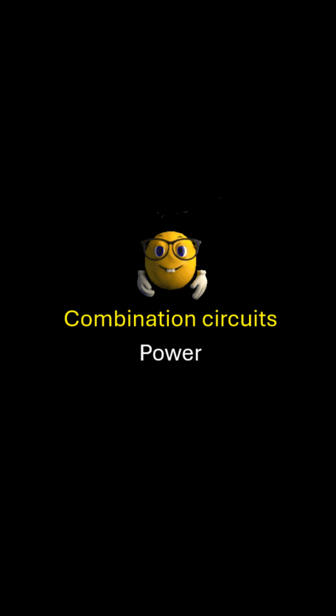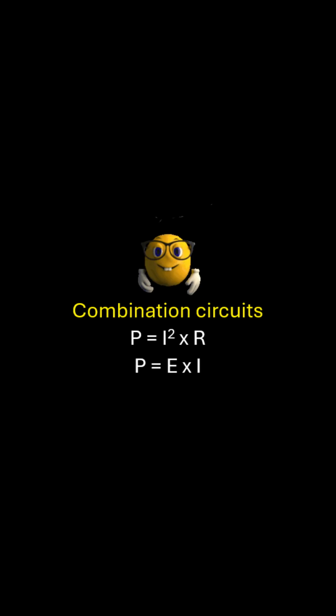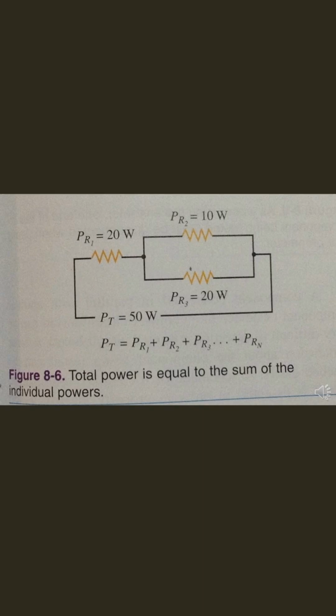Power in combination circuits. Power in a combination circuit can be calculated by using either the formula P equals I squared times R, or power equals current squared times resistance, or the formula P equals voltage times current. These formulas can be used for each individual resistance or for the circuit as a whole. Total power in a combination circuit is equal to the sum of the individual wattages, regardless of whether they are connected in series or in parallel. Figure 8-6 illustrates how power is determined in a combination circuit.